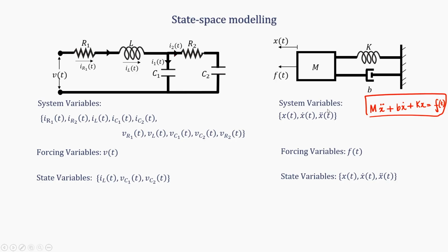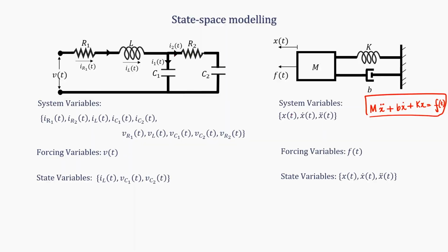Now, which are the 2 states you can choose? Generally for spring mass damper systems, position and velocity we choose. Okay. So, in this case there will be 2 among the system variables, you can choose 2 state variables. So, we will choose position and velocity. So, this will not be a state variable. Okay. This has been mistakenly written. So, this is not a state variable, remember. So, there are 2 state variables in this case, this is x and x dot.